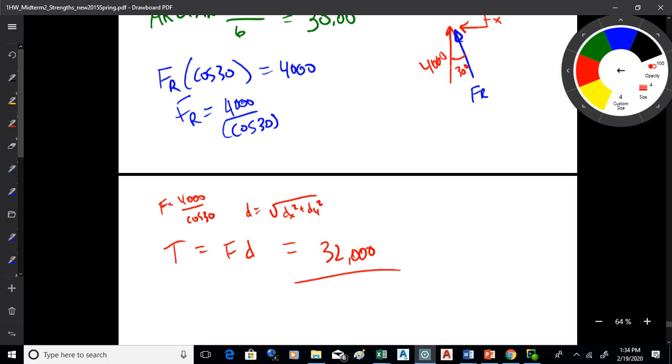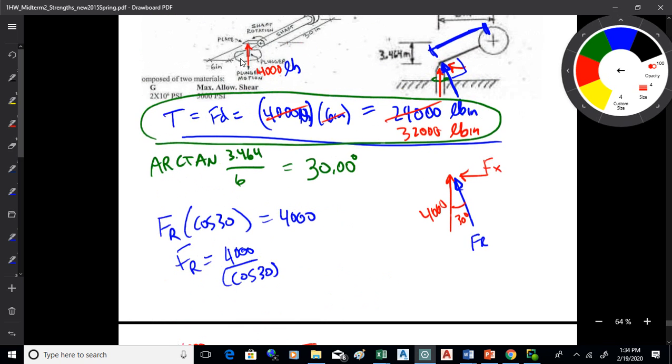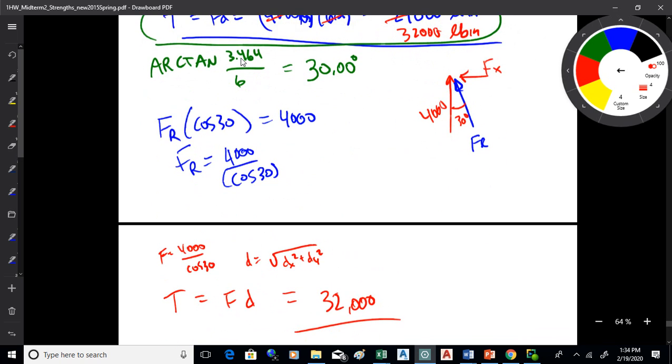Now, once you've got there, this is stuff that we've looked at a little bit before. You've got two criteria. One is very direct: the shear is 5,000 psi. You should be able to figure out the radius required for that. But what's the other criteria you have for when we analyze shafts? What are the two main things we look at?